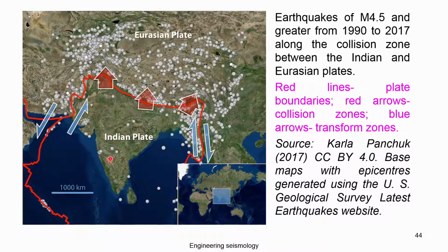Further, if you come down south, we have seen there are earthquakes here and here, but these earthquakes are generally intraplate in nature. These are earthquakes due to the activation of local seismic sources. Due to the bending action of the plate, because when it is going at speed and hitting there is a bending, that bending creates an additional force which activates some of the joints of the geological materials in central and southern India. Those also cause earthquakes.